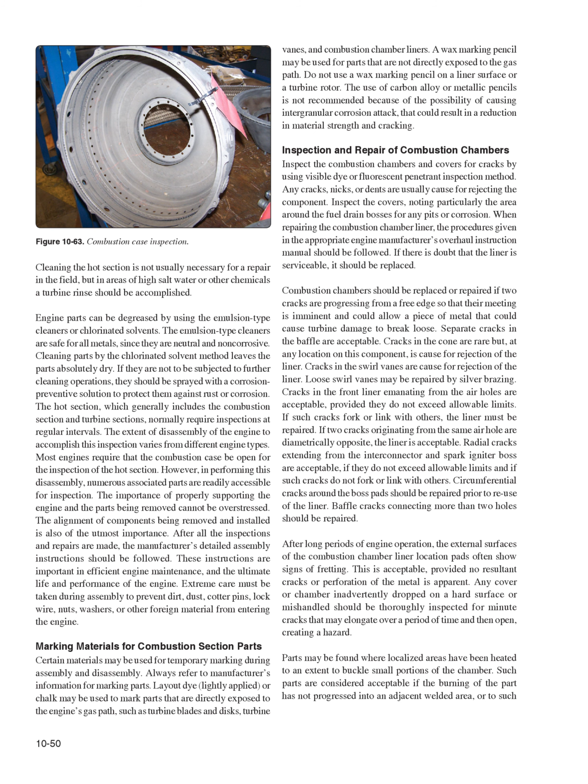The hot section, which generally includes the combustion section and turbine sections, normally requires inspections at regular intervals. The extent of disassembly of the engine to accomplish this inspection varies for different engine types. Most engines require that the combustion case be open for the inspection of the hot section. However, in performing this disassembly, numerous associated parts are readily accessible for inspection.